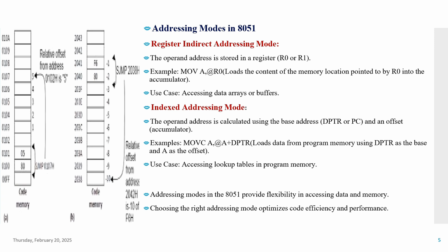Now the next part is register indirect addressing mode. Discuss how different addressing modes are utilized in programming the 8051 microcontroller. Clear? And indexed addressing mode means the operand address is calculated using a base address, that is DPTR or PC, and an offset.